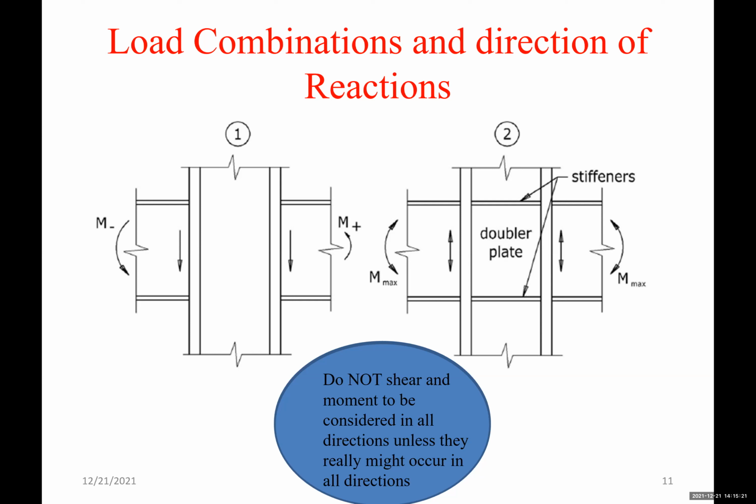The reaction directions. It depends whether we have a cyclic loading on the members, like in the case of earthquake or wind, or whether we have gravity loads. So show the reactions of your forces on the drawings to allow the connection designers to understand how the moment is applied, where's tension, where's compression, and let them design for that. So there is no need to design for cyclic moment if it's just a gravity connection.